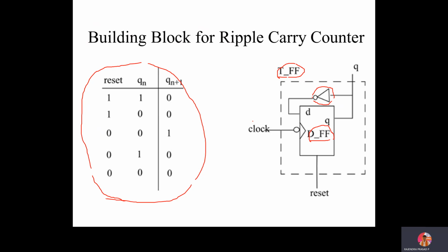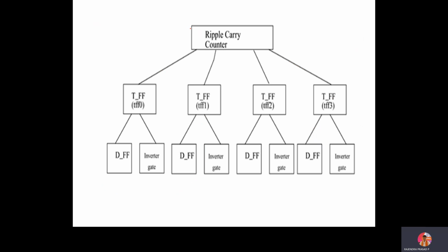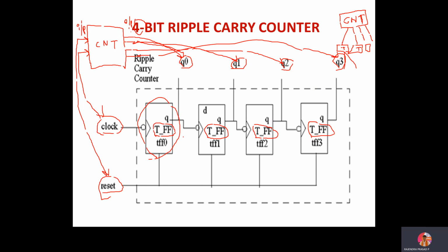Now, looking at this block diagram, I can implement the top-down approach or the bottom-up approach. So how will that block be? As I said at the initial part, it will be a ripple counter. My sub block will be a T flip flop. How many T flip flops? There will be four T flip flops which I'm going to use, as can be observed in this block diagram.